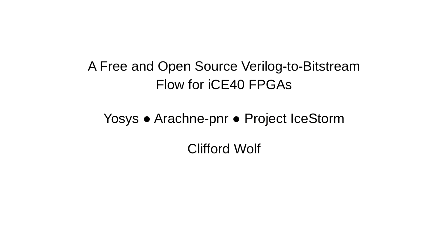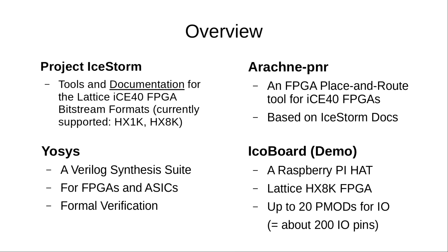Thank you. So I'm talking about the free and open source Verilog to Bitstream flows for iCE40 FPGAs. In particular, that means I'm going to talk about 3 projects, because these 3 projects together form this free and open source Verilog to Bitstream flow for this kind of FPGAs. The projects I'm going to talk about are Project iStorm. And Project iStorm is an effort to reverse engineer and document the bitstream format for iCE40 FPGAs.